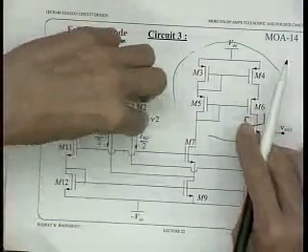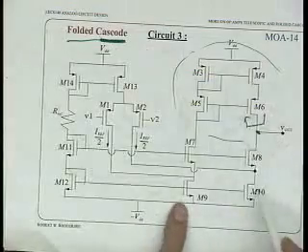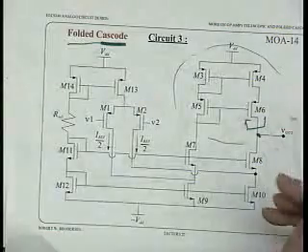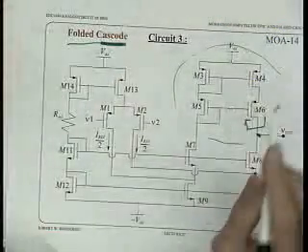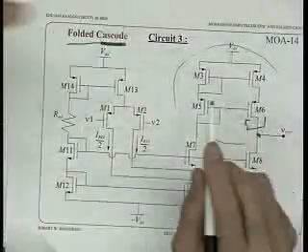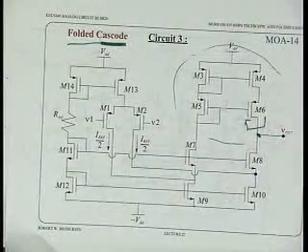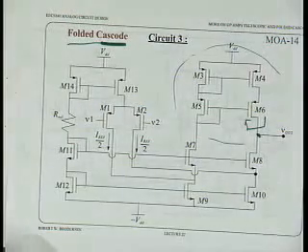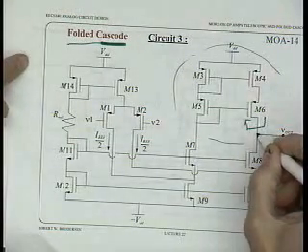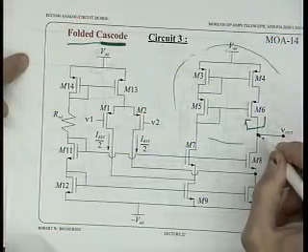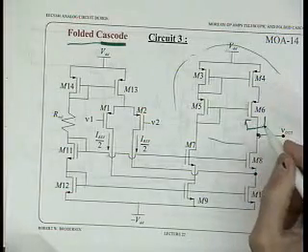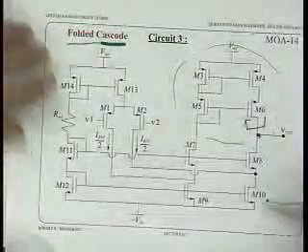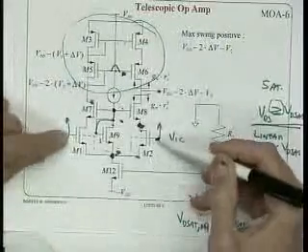So basically it's just a good old differential pair. The trick is that you can fold a current like this, and what's kind of weird is, well, you think, geez, what's current going upwards? But remember, this is small signal, right? Right? Yeah. So the swing on the high part of Vout is actually the same as circuit 2 that you showed, right? We don't gain any swing from the folded cascode on top, like from M4 and M6. Right. Yeah, we haven't won there at all, right? Where we've won is on the other direction, right? Because we got rid of this common mode voltage problem, right?